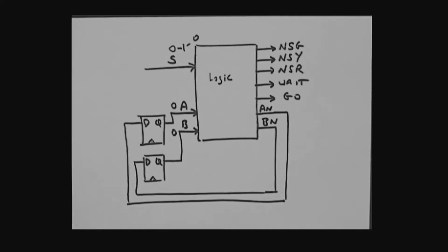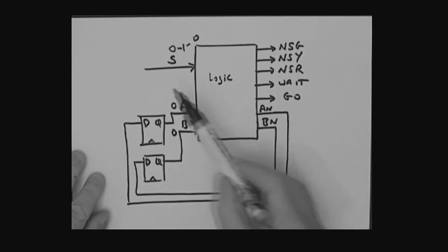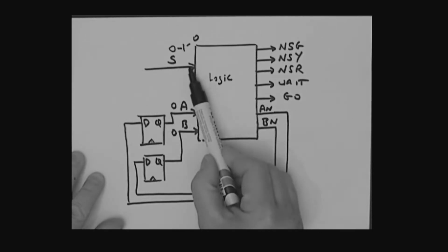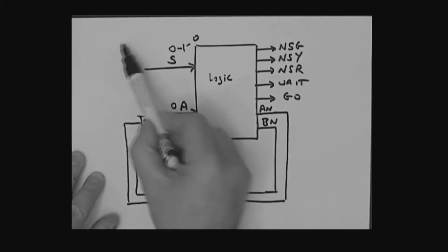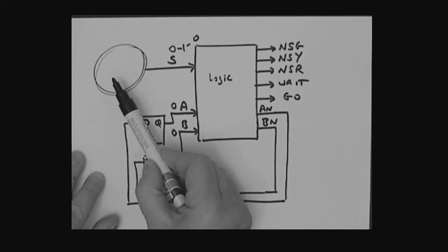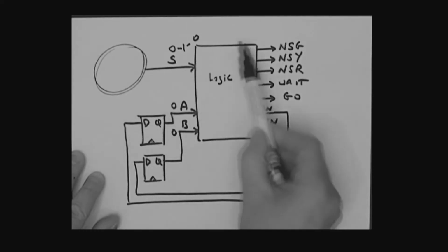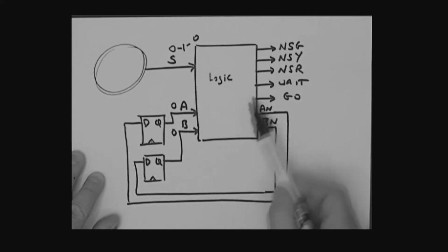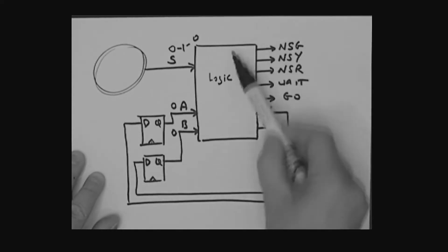All right, let's go back to our state machine again. Now, I'm going to use an SR latch to do what? Well, somebody's going to press the button. We want to latch that signal in, don't we? And then we want our state machine to perform a resetting function at an appropriate time. So the question is, what do I do over here? How do I use that SR latch with, let's say, a push button type switch in order to provide the input into this combinational logic, or as an input into my complete state machine?